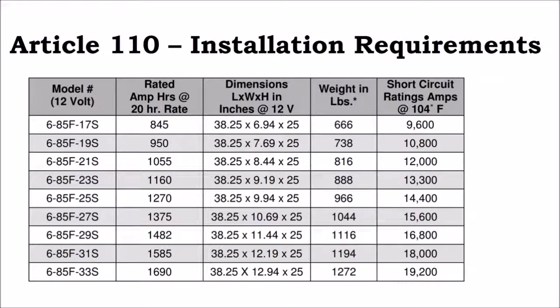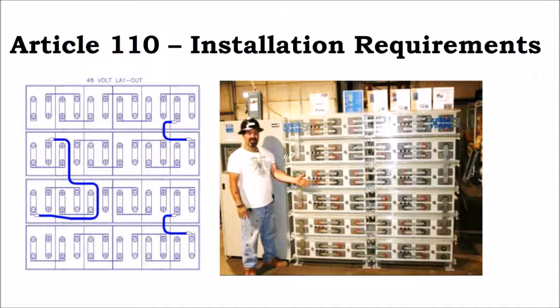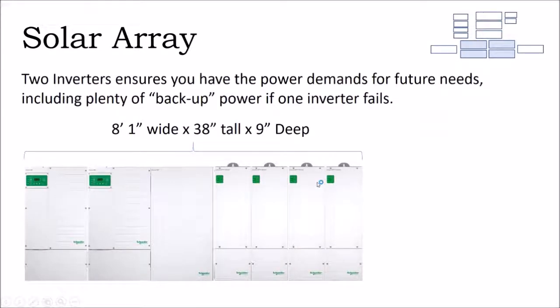And also just the practical element of how are you going to get the batteries to the room if you're using heavyweight batteries? Those are issues we talk about more in the battery management class, on why you might choose a 2-volt battery to have 48 batteries in your battery bank instead of a 12-volt battery and have 8 batteries in your battery bank. It's all about, can you move the batteries around, or do you have to carry them in? If you have to carry them in, you might go with the smaller, more lightweight battery and have dozens of them.